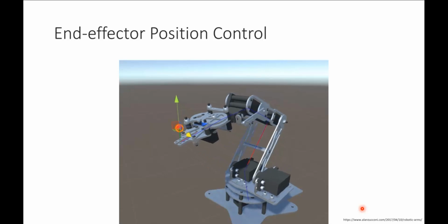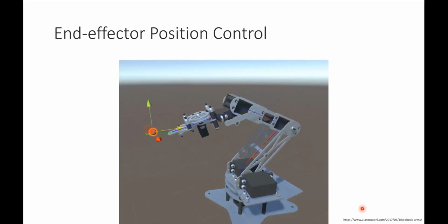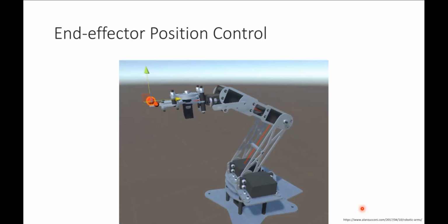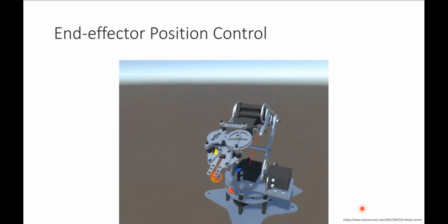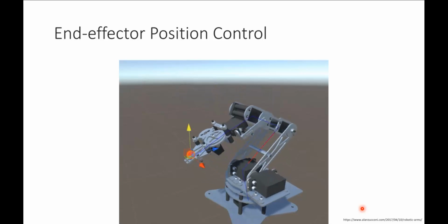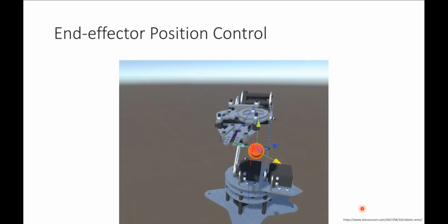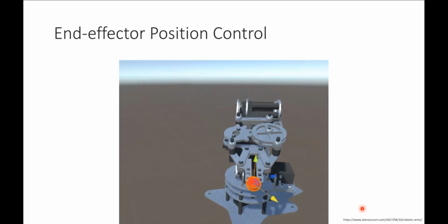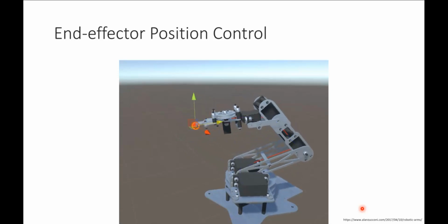So towards the end of last lecture, we looked at this example of end effector position control that we could use, say, using an inverse kinematics controller. So what's happening in this demo is that the X, Y, Z position of this little ball is being reported back to the software, which is then running it through an inverse kinematics function to get joint angles for the robot. And then the robot is just interpolating to those points. And so we might run into trouble though.